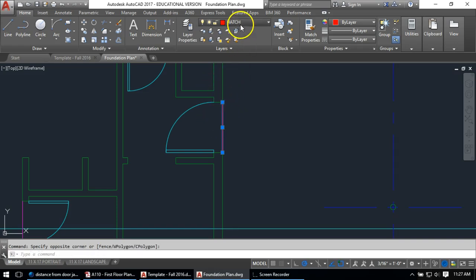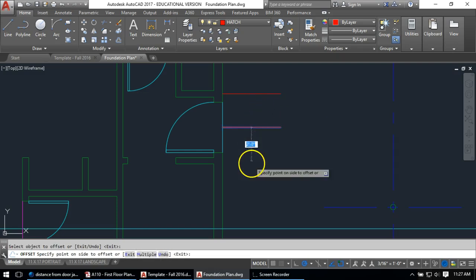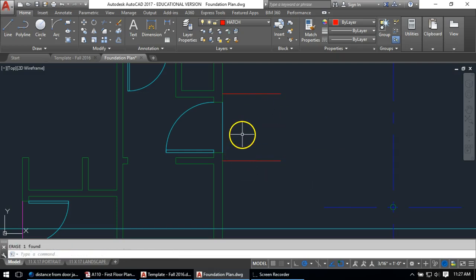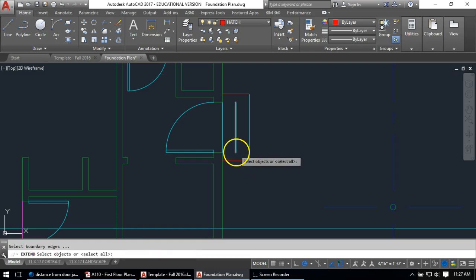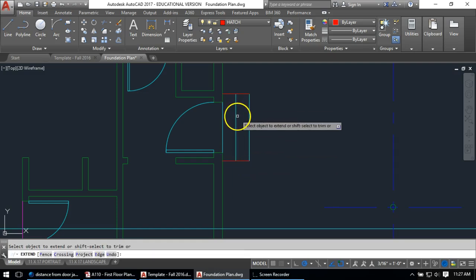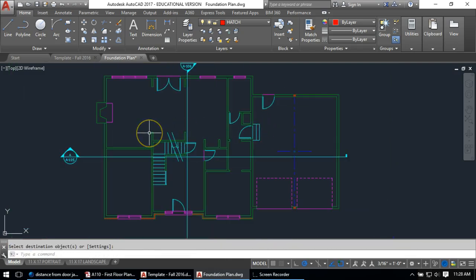I'm going to put it on my stair layer, the one we're using is medium. I'm going to mark a line over and offset 2 feet. Make that assumption that they're 4 feet wide, and that each stair will say is 10 inches wide, just like before. So I need to come out 2 offsets to draw that shape in. Here and here, extend and extend. There and there. Match that to draw that set of stairs there. Alright, pretty good, pretty good.